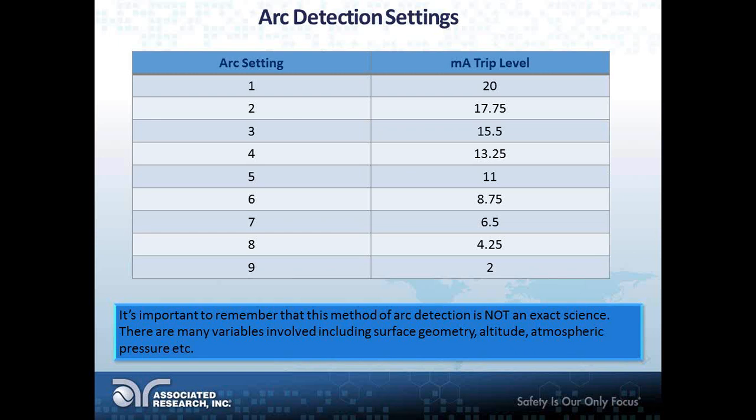Like, oh, I'm getting an arc fail, I don't know what's wrong. What I usually have them do is, okay, Mr. Customer, go in there, turn arc fail off and run your test again, and lo and behold, it passes. That's because the unit is picking up some buildup of corona, and it could be some significant spikes, but the insulation is actually still fine. It's still intact, and they're well within the leakage limit. So that's an important distinction to make.